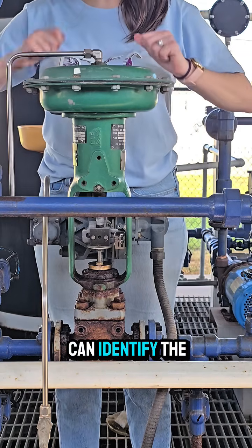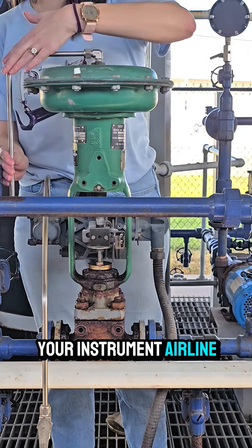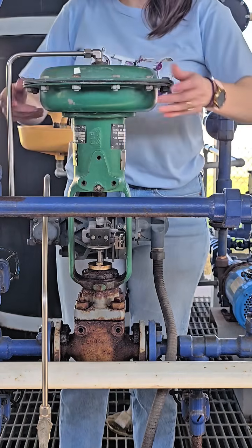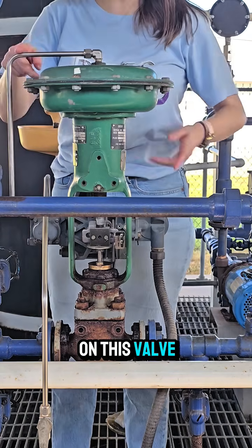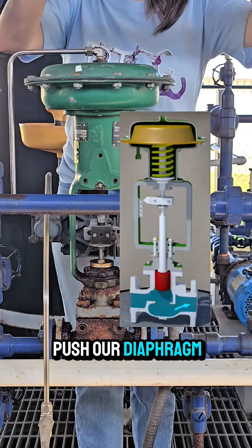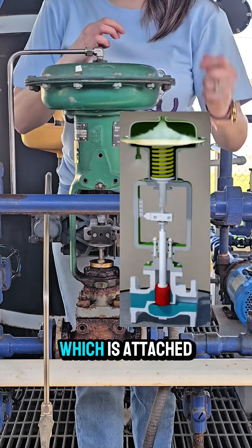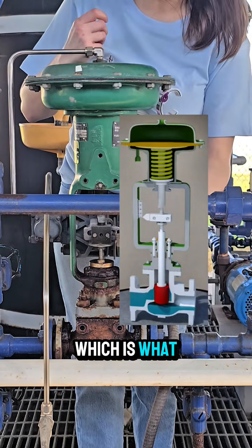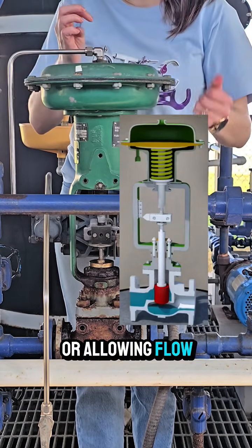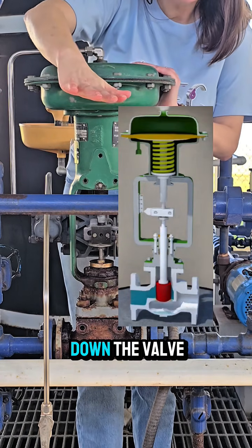The way you can identify the fail position of an automatic control valve is where your instrument air line enters your diaphragm. Our instrument air line on this valve enters the top of the diaphragm. When air comes in, it's going to push our diaphragm plate down. Our diaphragm plate is attached to the stem, which is attached to the plug, which is what is blocking flow or allowing flow. So when the diaphragm plate is down, the plug is down, the valve is closed.